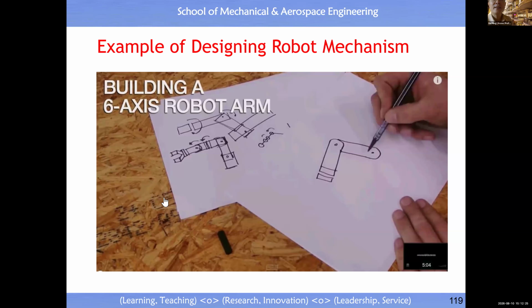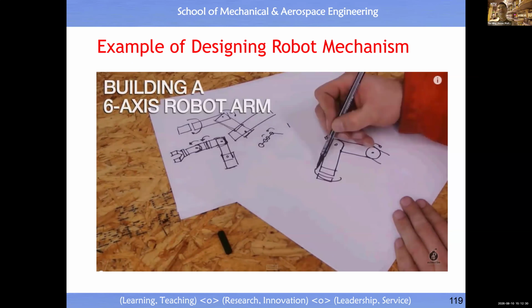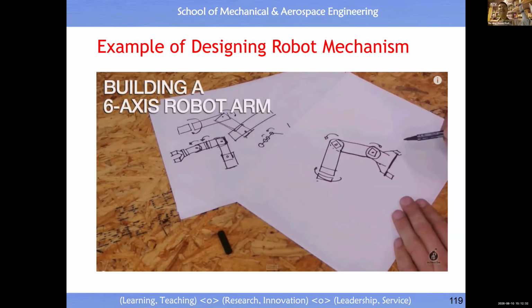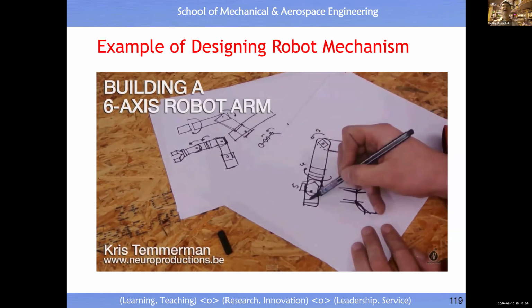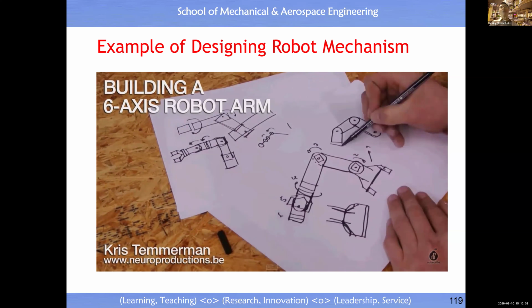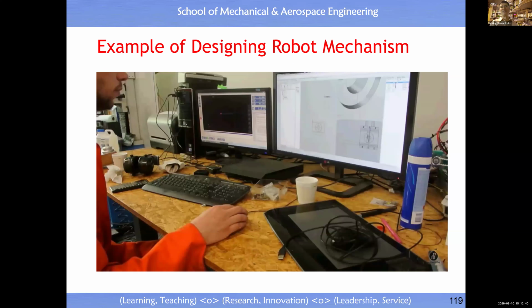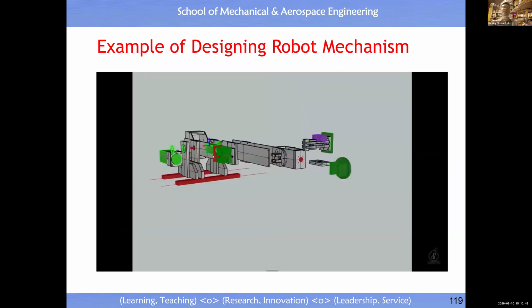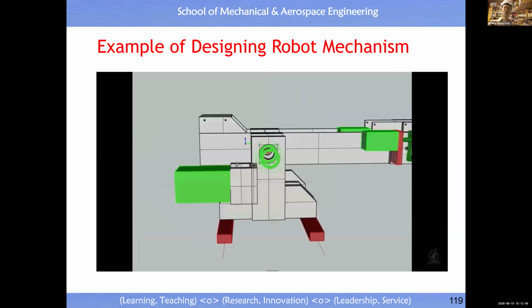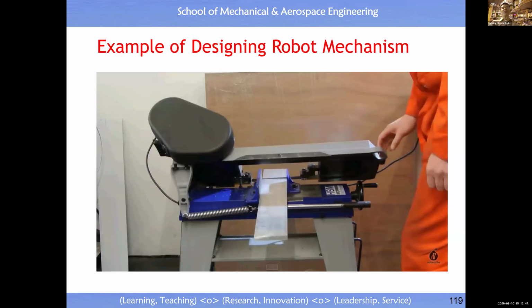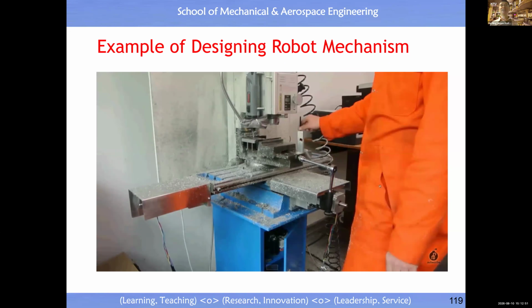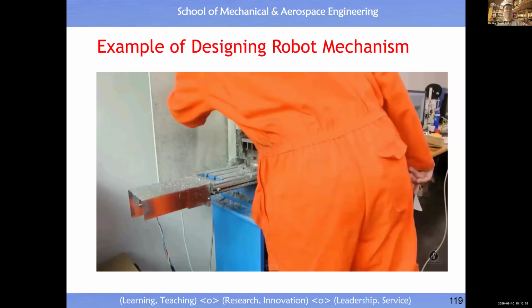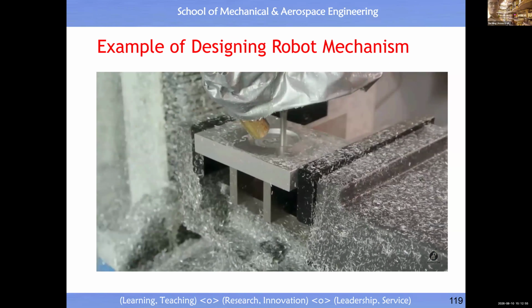So, conceptual design. Then you choose the actual one, then you come out with the embodiment design, then part drawing. You see this is the embodiment design, 3D view, then part drawing. Once you have a part drawing, you trigger assembly and fabrication, guided by your part drawing. But this is a compressed video, just highlighting the key steps.